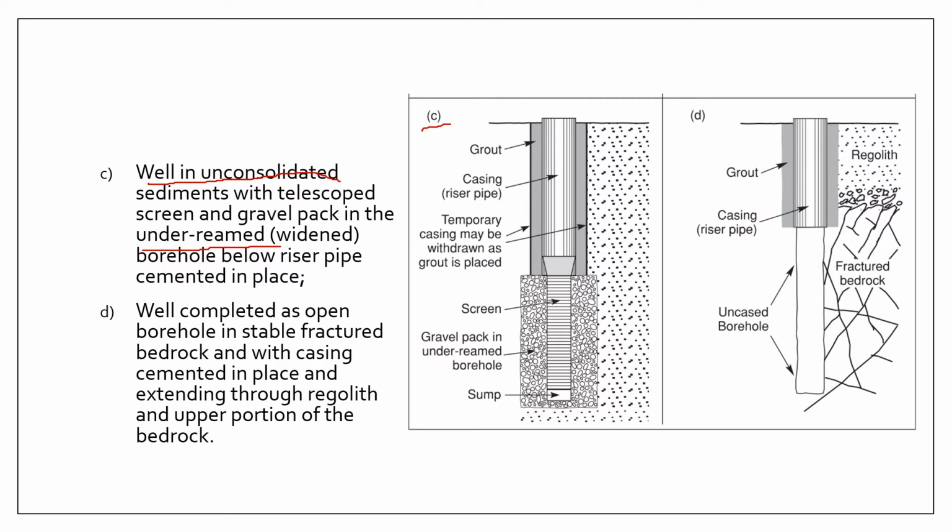And the second reason is to make room for your gravel pack. Your gravel pack is like the first line of defense for stabilizing the aquifer formation as well as providing filtration.